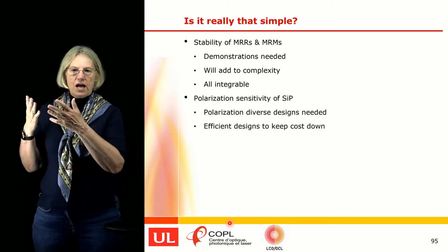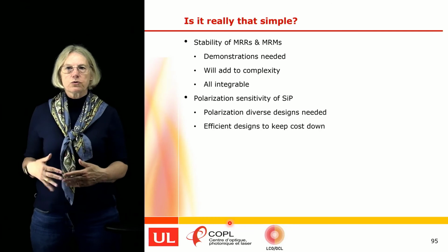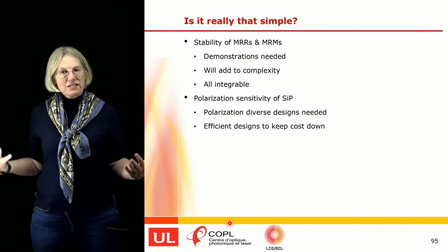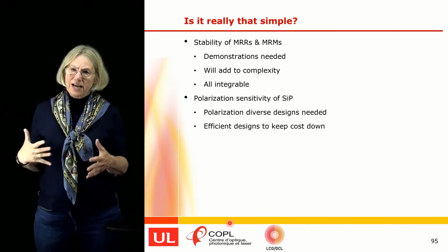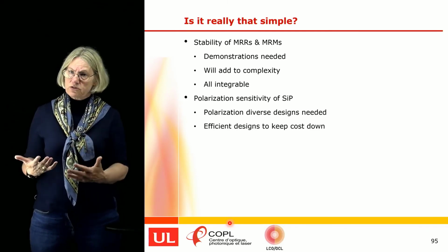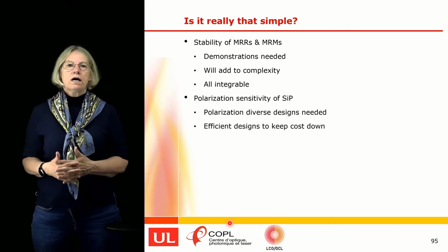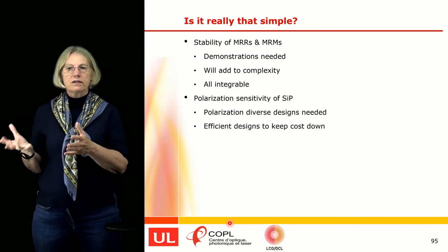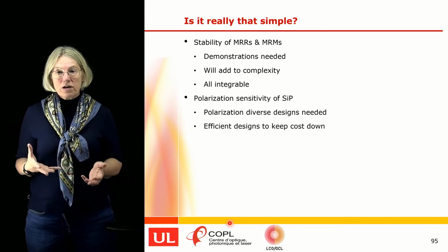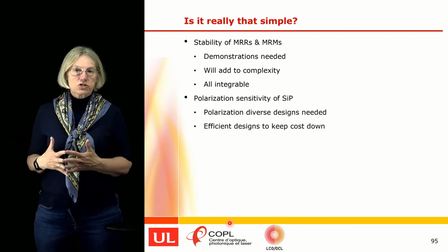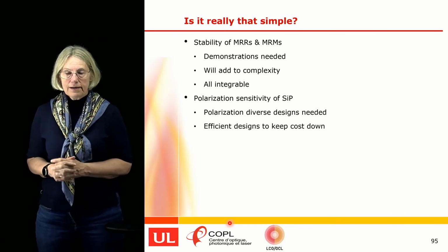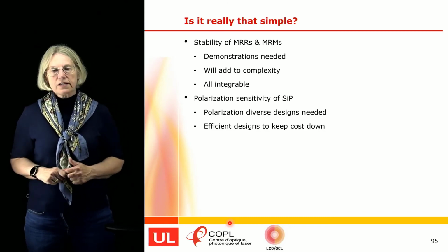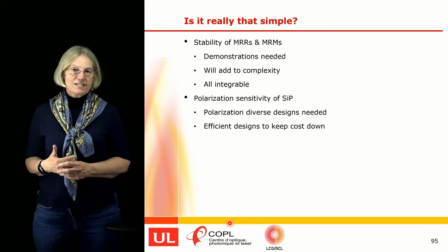So certainly we have used on-chip monitoring diodes, photodiodes, in order to create a feedback signal. But as we scale to more and more channels, and we have more and more resonators, we want to keep the footprint small so they're packed closely, and there's a lot of thermal crosstalk, so we need some more demonstrations that show that this is as scalable as we believe it is. Certainly more control will add to complexity, but as this is completely integrated on silicon, it could have the feedback control signals in CMOS. They're very slow, so they should not add to the cost significantly or the power consumption overly.